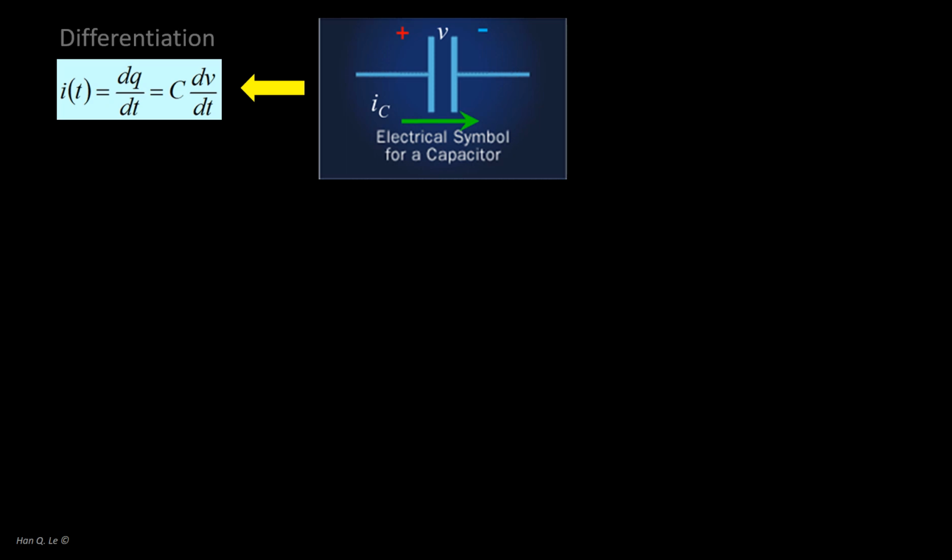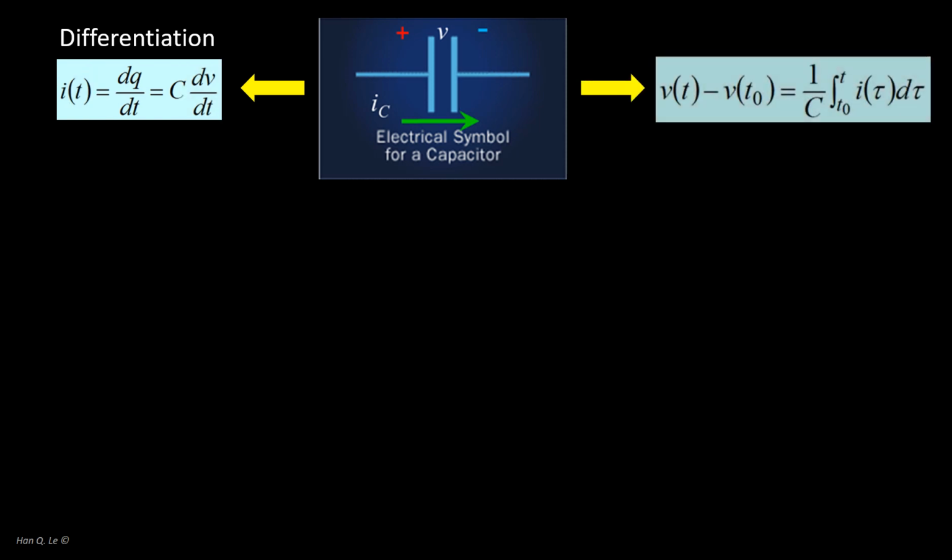Consider the capacitor. The most basic property is the relationship between current I and voltage V, which is a differentiation. The relationship is written with an implicit notion that V is the primary entity or input, and I is the derived entity or output. It is just as equivalent if the relationship is reversed. Let I be the primary or input, then V is the derived or output, then the mathematical operation is the inverse of the previous, that is, it is an integration.